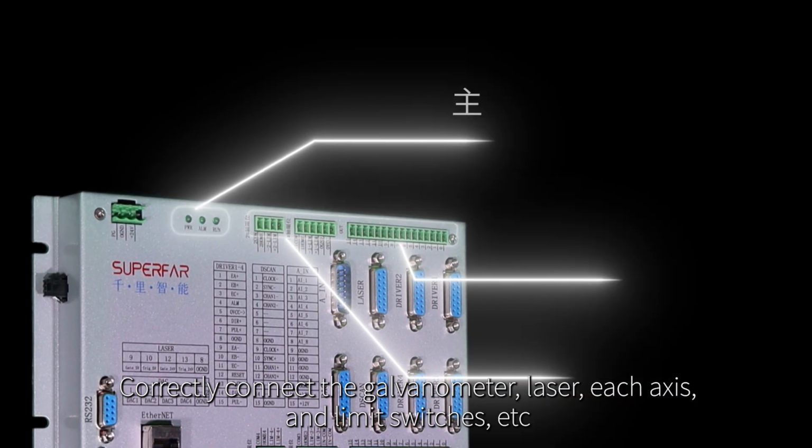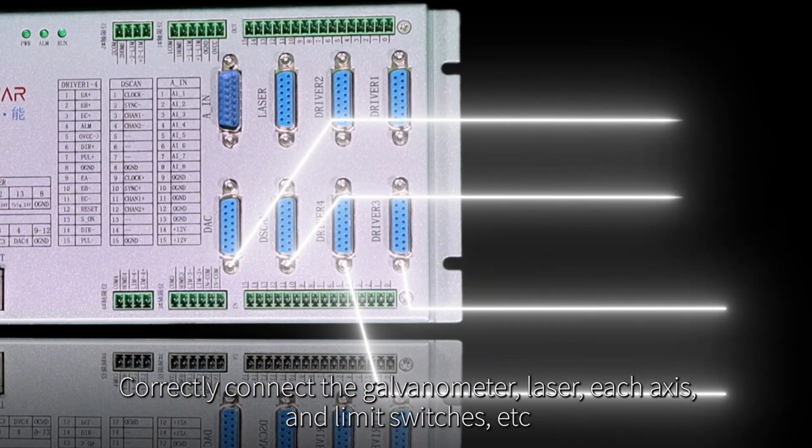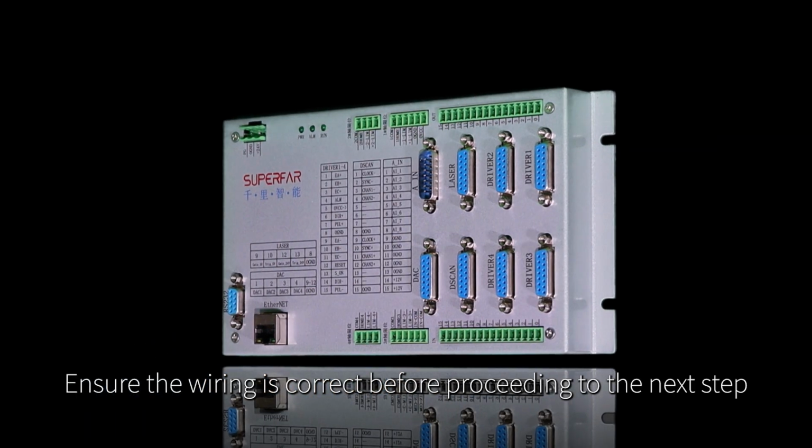Follow the hardware manual step by step. Correctly connect the galvanometer, laser, each axis, and limit switches, etc. Ensure the wiring is correct before proceeding to the next step.